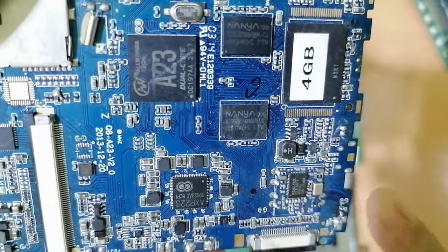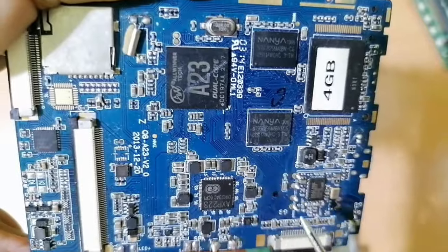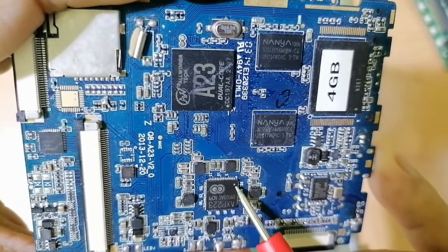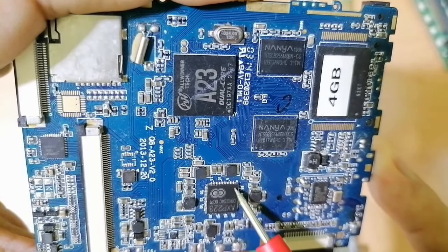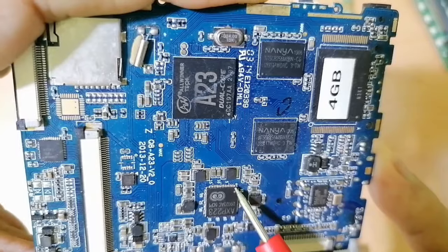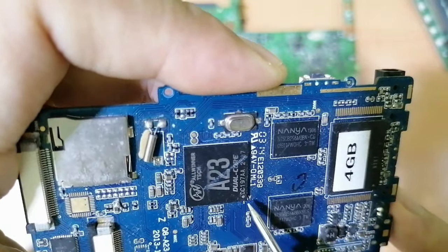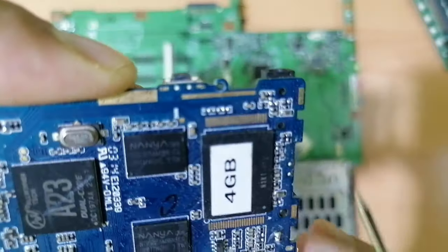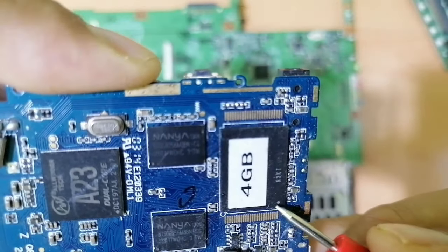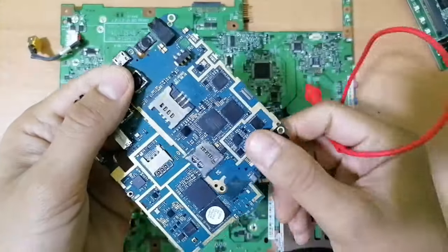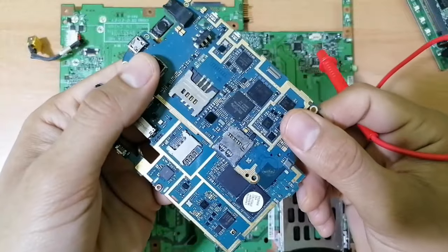So if we go to the tablet motherboard, as you can see, it's the same working principle. We don't have a hole, but we have this point. This dot here means over here we have pin number 1. The same, for example, for this processor, we have a dot here, okay? The same here, we also have a dot. So for the cell phone motherboard, as you can see, we have the same working principle.